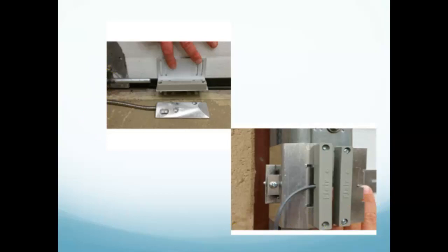As you raise an overhead door, right? Think about your garage door now. As you raise up a garage door, there are channels on either side the door travels in, and you will see contacts that mount that way. One stays stationary on the channel itself. The other one is bolted to the door, and when the door lifts up, this one goes up. The reeds inside here open up, and the alarm goes in.